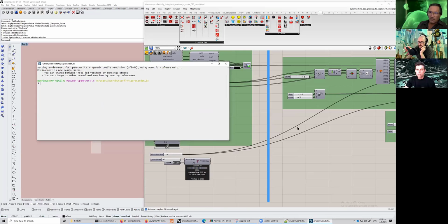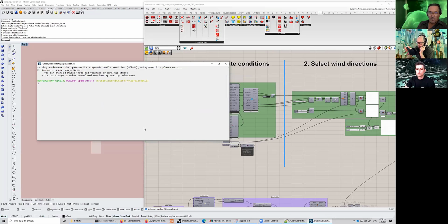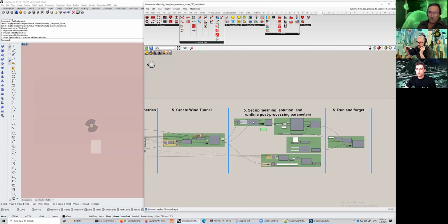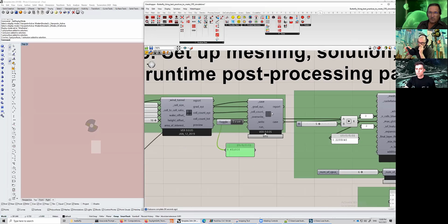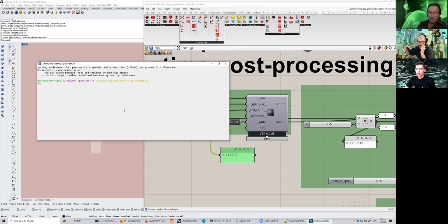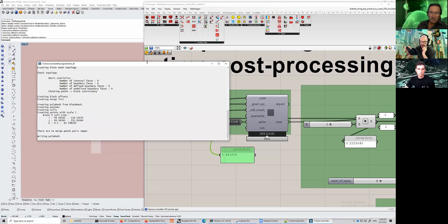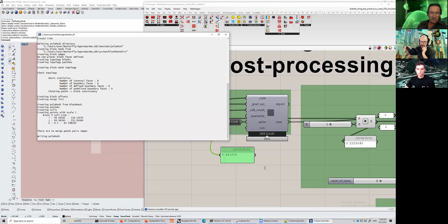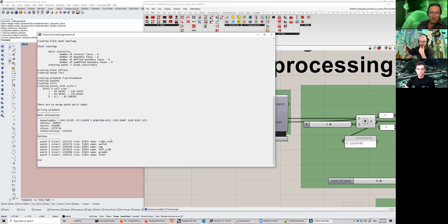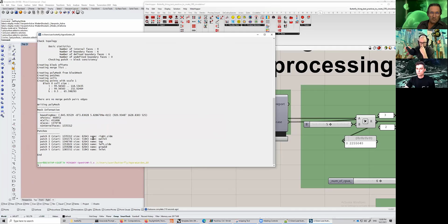So the first component, and I will open it here, is this blockMesh. The first run is in the component called blockMesh, right? And very conveniently, the command is actually blockMesh. So right now I'm writing OpenFOAM commands, right? And this is what Butterfly runs in the background. If I press blockMesh here, it will start popping up some numbers, and very quickly it will generate something, right? And after you do OpenFOAM for a while, you will start reading this and understanding what this is.